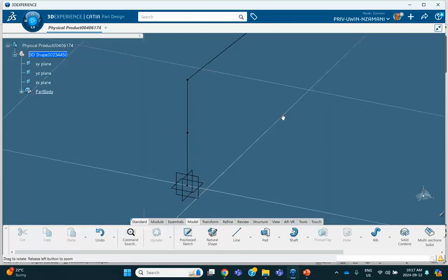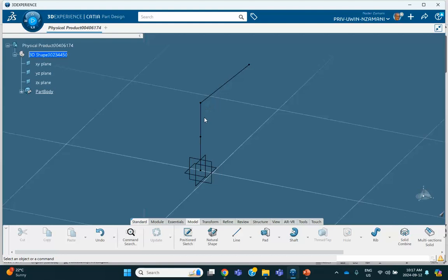So there's my geometry. Now I'm not going to join these things. And when it comes to meshing, by the way, I'm going to make sure that the checkbox is off so that I get duplicate nodes at the two ends, at the two sides. Okay. So let's apply our material properties. So, tools.